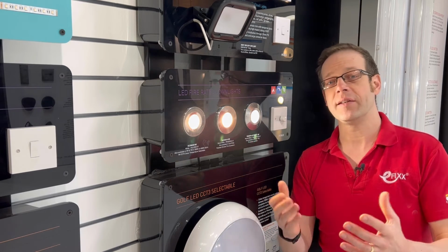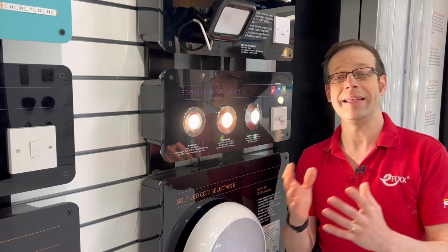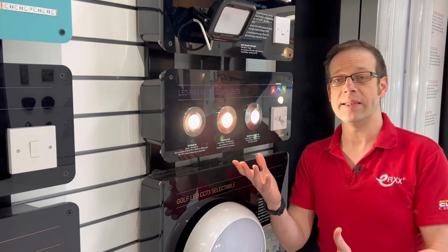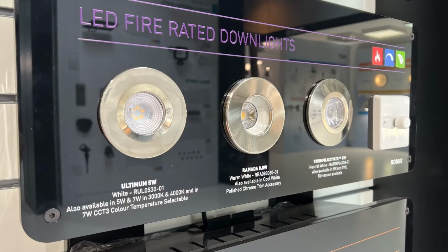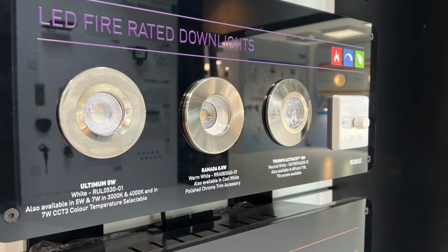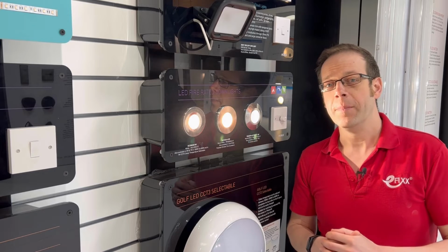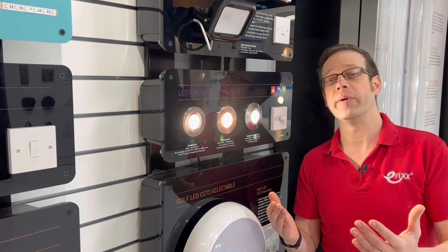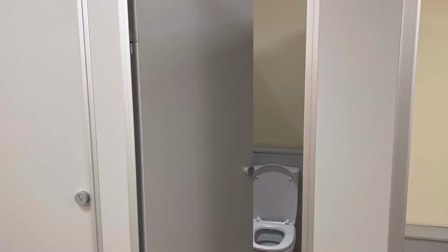In addition to this, lighting can be split into further categories, each of which can be represented in each of these environments. So in the downlight category, you'll find small recessed spotlights that are perfect for installing in domestic and residential properties. These are usually fire rated to help prevent the spread of fire and the collapse of ceilings that have rooms above them. But you'll also find in this category larger recessed fittings that may be more appropriate for installing in commercial properties for use in corridors and ancillary rooms like kitchens and toilets and things like that.